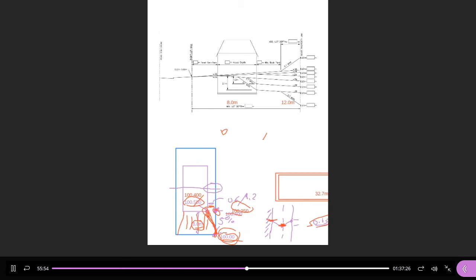If I want to maximize how high I can be at the back, I'm going to use 3%. So 3% for the front yard, 3% all the way to the back of the building, and 3% all the way to this point here, the minimum point where the minimum backyard is achieved. So what's the elevation of that point there? If I come up 3% all the way to the minimum usable backyard point, what's the elevation here?